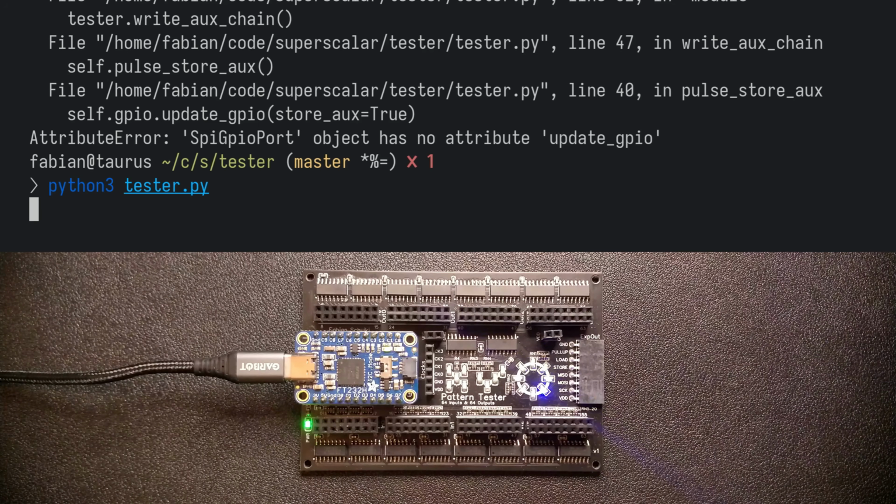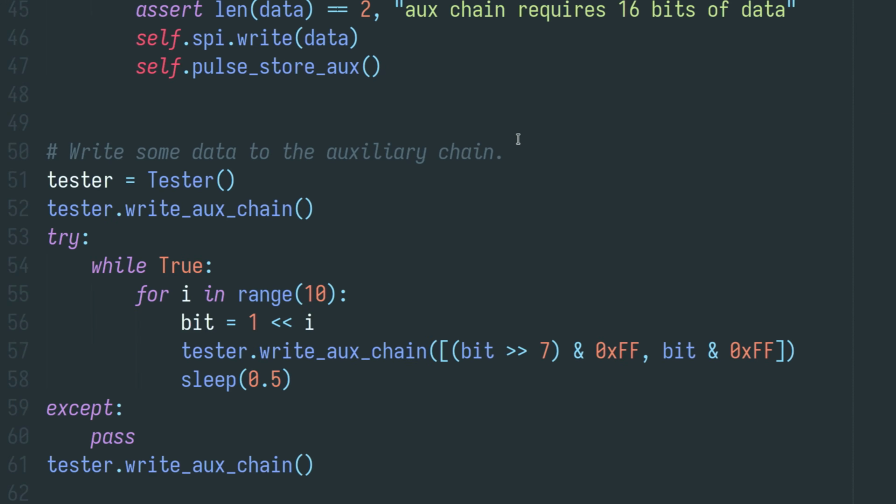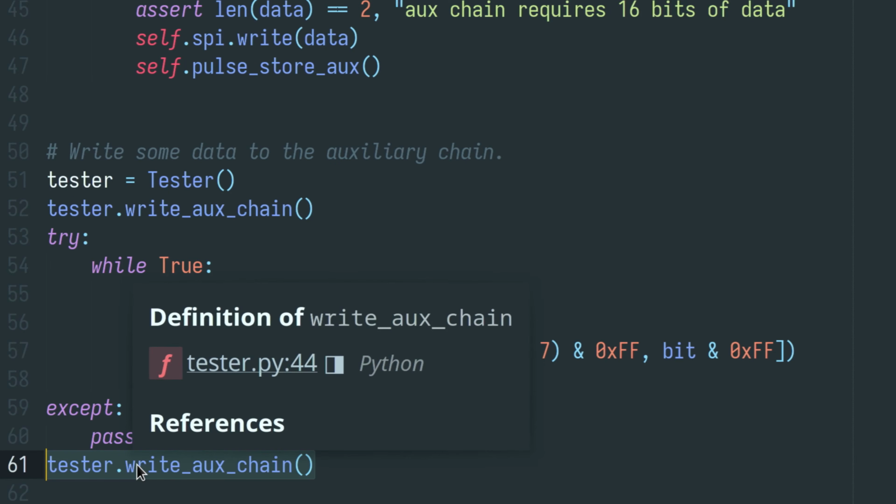And if I now cancel out of the script, we should see the LEDs turn off instead of just the last one that was lit remaining on. And there you go, hitting Control C, basically aborting the Python 3 execution, is triggering the exception. And the exception we intercept with this try except block here and basically do nothing and just continue with this part down here, which is clearing the LEDs back to 0 again.